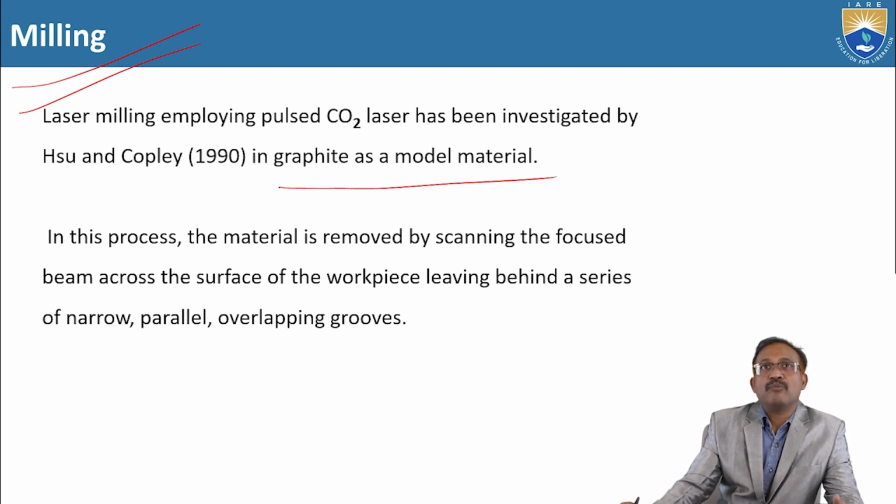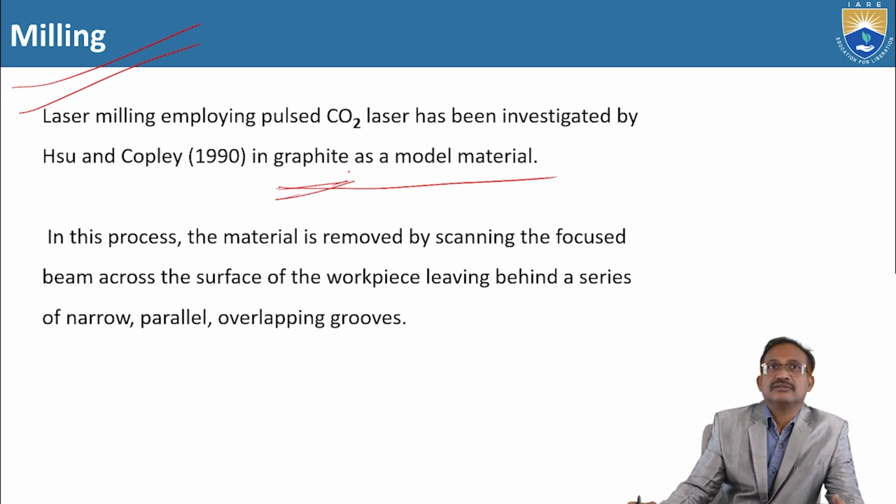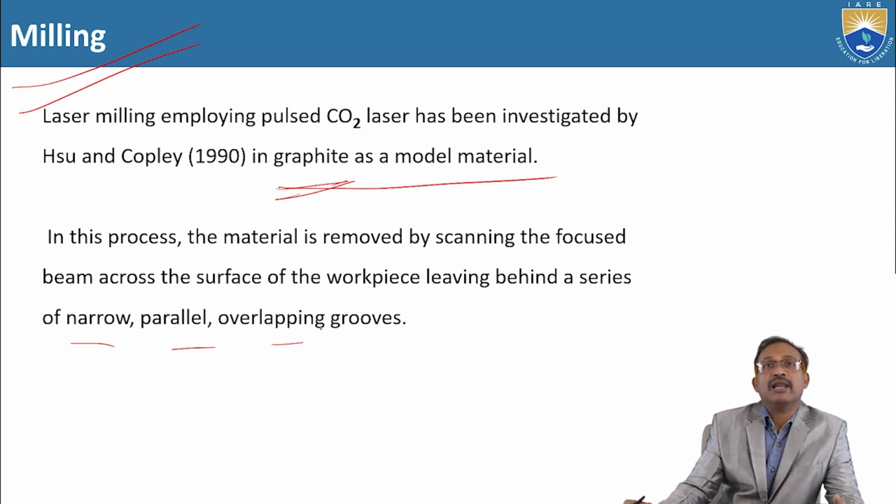In this process, the material is removed by scanning the focused beam across the surface of the workpiece, leaving behind a series of narrow parallel overlapping grooves.